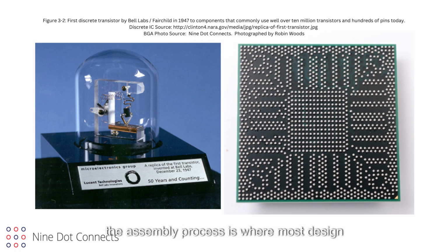Note that the assembly process is where most design projects crash and burn. The term respin is used to describe the process of fixing the issues of the board found in the manufacturing process, and then resubmitting the corrected documentation for another fabrication and assembly effort. The respin effort can range from a minor landing size correction, to a complete component placement modification, and rerouting of the board.